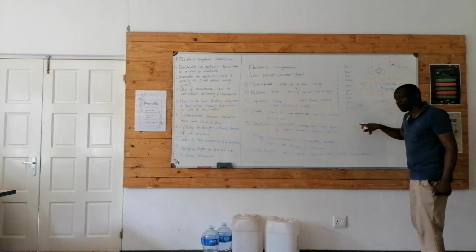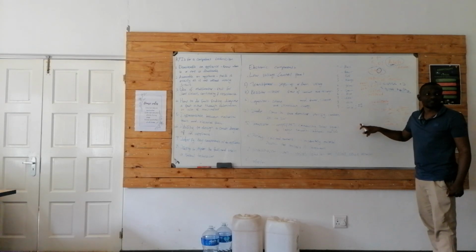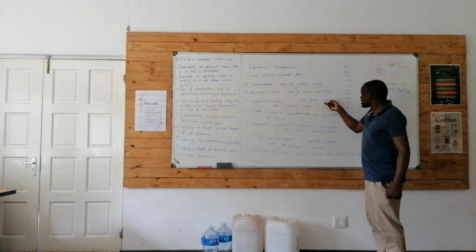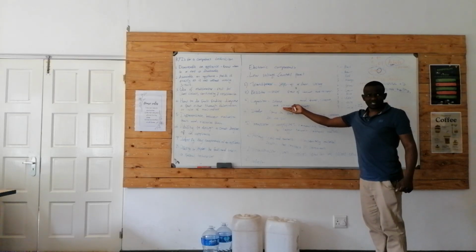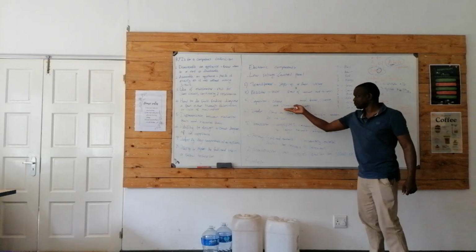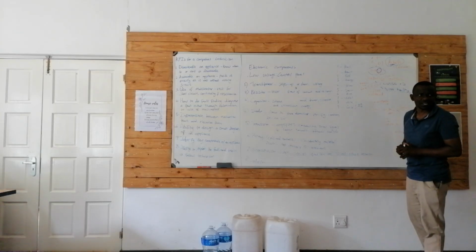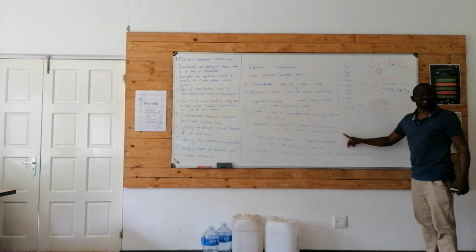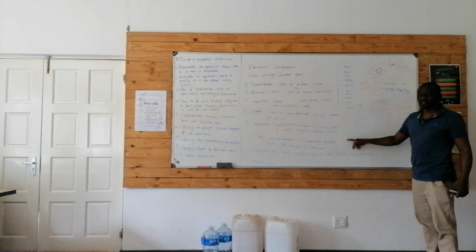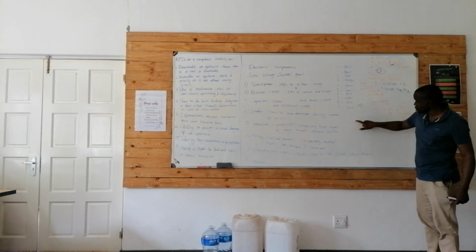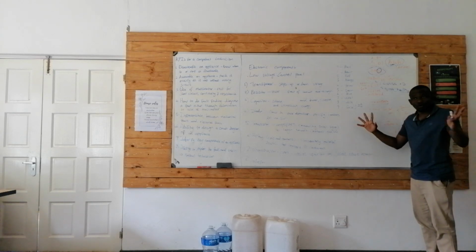So that's the component that you need to replace. Because capacitors act as filters, smoothing the electric current. So if it's like this, the flow is affected, it won't work if the capacitor is damaged. So you'll see it expanded or it will blow.